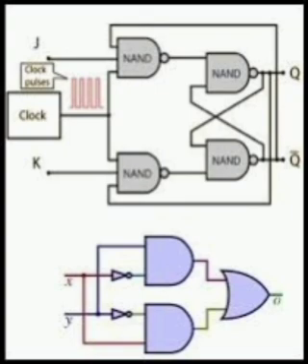Given mux 8 is to 1 to be implemented mux 256 is to 1, 32 plus 4 plus 1 equal 37. To implement 2 power n is to 1 mux by using 2 is to 1 mux, the total number of 2 is to 1 mux required is 2 power n minus 1. Mux is a universal logic gate.